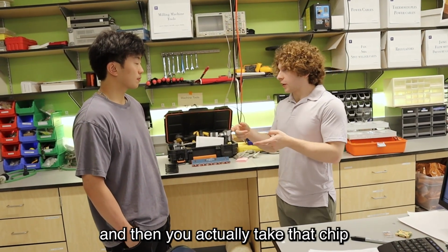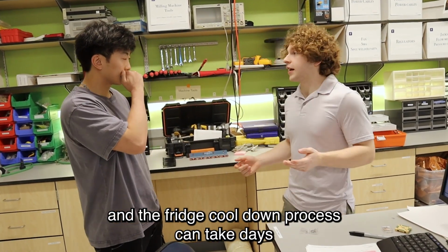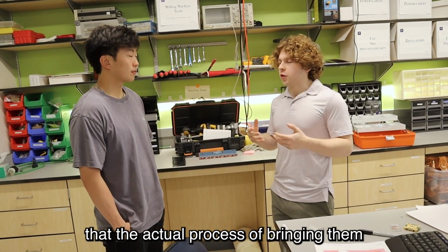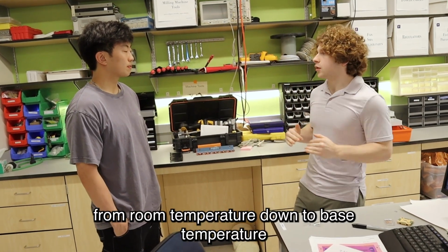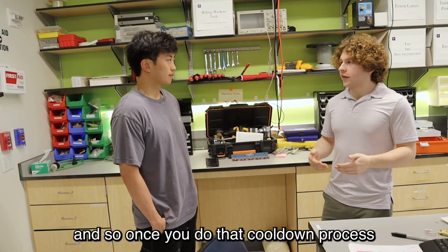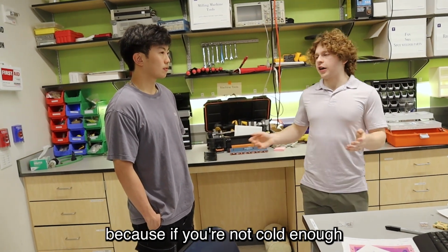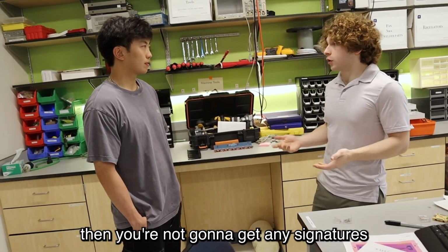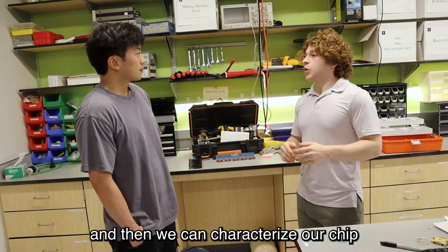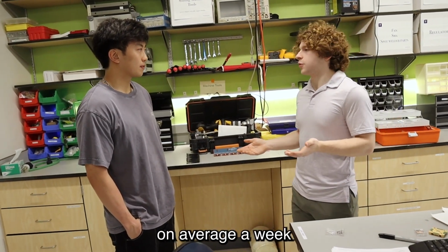And then you actually take that chip and you put it in the fridge and you cool it down. The fridge cool down process can take days. These fridges are getting to such cold temperatures that the actual process of bringing them from room temperature down to base temperature can take 1 to 2 days. Once you do that cool down process, then and only then can you actually do the measurement, right? Because if you're not cold enough, then you're not going to get any signatures in the device. And so we get down to this base temperature, and then we can characterize our chip. And that whole process, again, takes, on average, about a week.